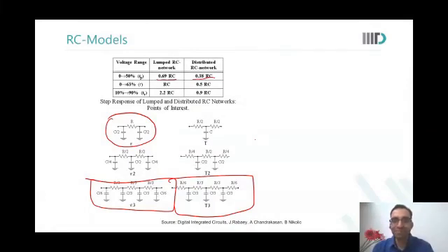Raghav? Yes, sir. So this pi model and distributed RC are two different things. Distributed RC, as I just explained, at every turn, every via, assumes a separate wire, and it will make an RC for it. Even for the via, because a via has a different resistance model. If you open the DRM of any technology, you will see that contacts and vias have a completely different resistance profile than wires. But they are also copper, right? So why is it different?